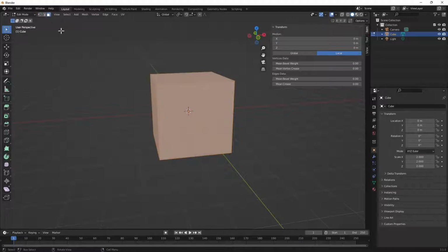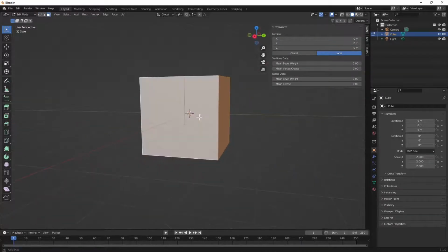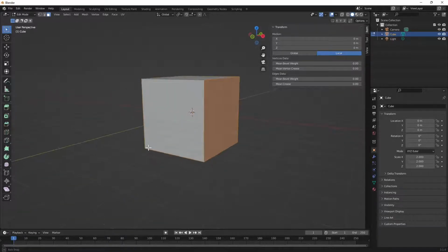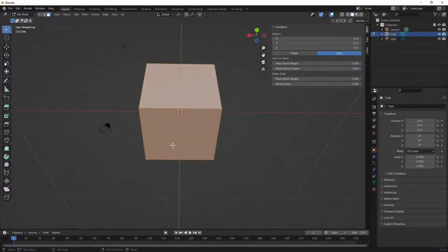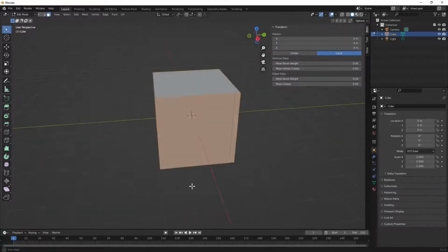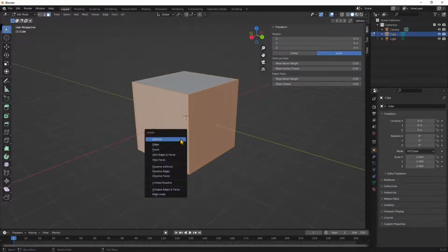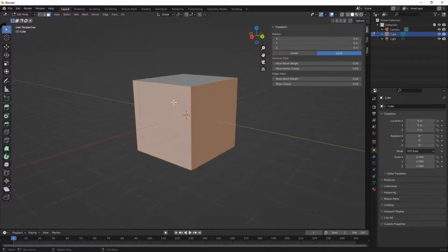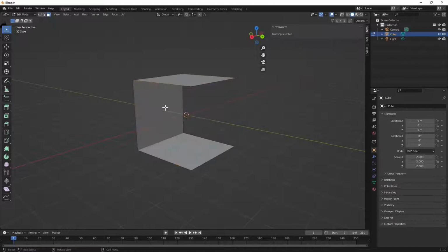We'll select all the faces here, and now with the shift key I'm going to start to select the faces that I want to keep. I'm going to keep this one here, this one here. It's like creating a C letter, and I'm going to press delete and get rid of everything else, and not the edges, sorry. So delete faces.